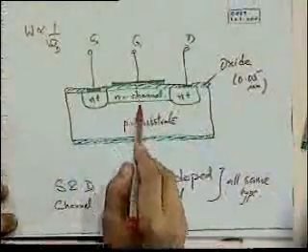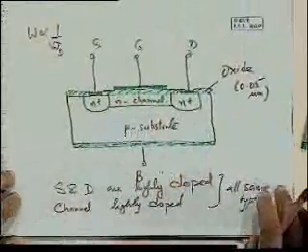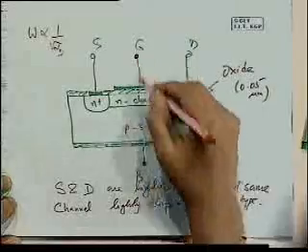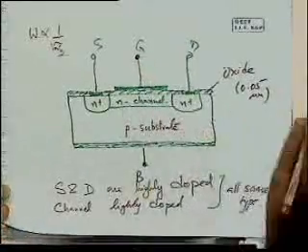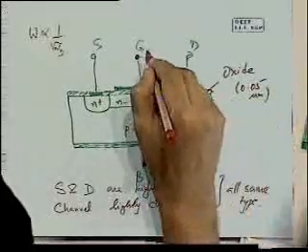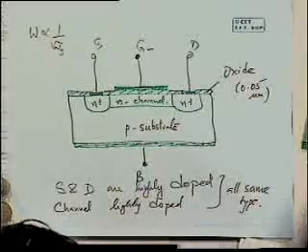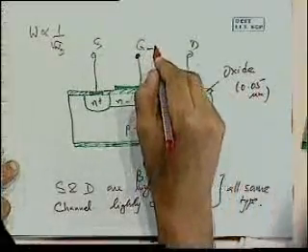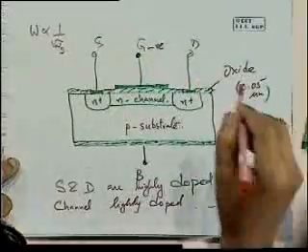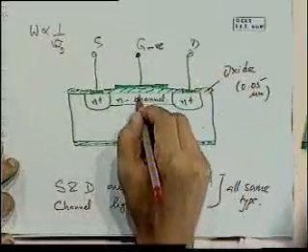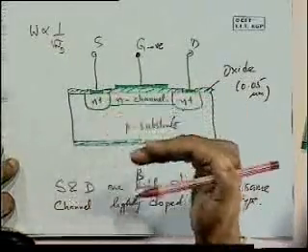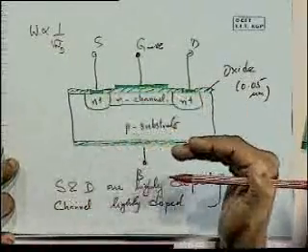And as we can see here, the channel width is going to be controlled by the voltage between the gate and this body. If we make the gate negatively charged, okay, we apply a bias so that the gate is negatively charged, then electrons are pushed away from this channel into the P. They're repelled by the negative charge there, and they're pushed away from there.